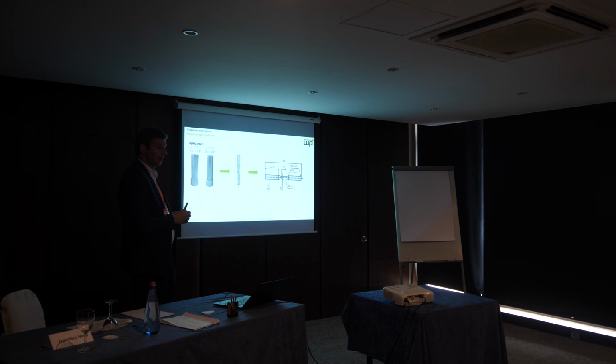No. It is not accurate. That's a big problem, because with the thermal camera you have a very poor spatial resolution, because you just have 640 pixels, and that will be hard to detect small defects. And his current, I thought it was 0.8 amps. It's pretty low, yeah. So perhaps you have to push it up to 8 amps or some higher current to see